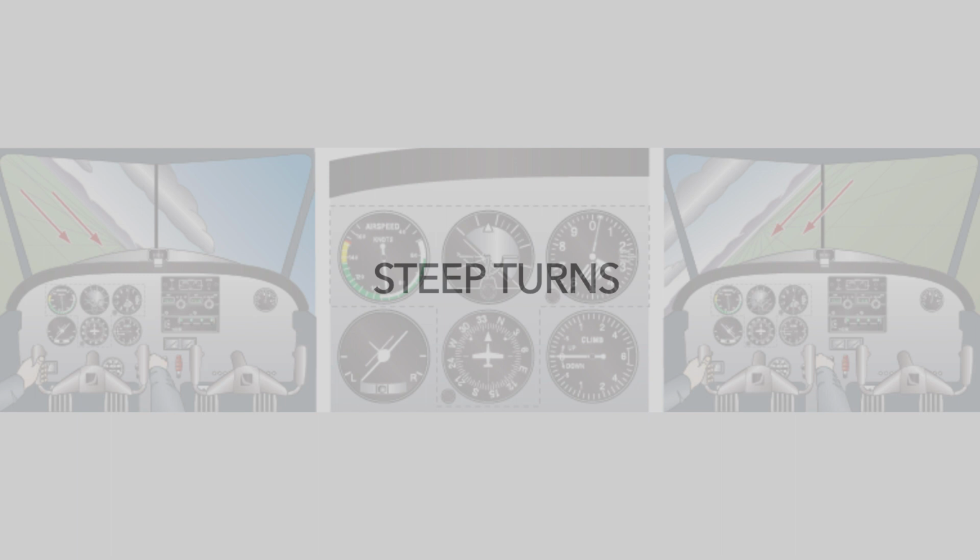3. The byproduct of increased angle of attack is induced drag, which steals energy from the airplane. In order to avoid decelerating and losing altitude, additional power must be applied to rebalance the forces. 4. In a steep turn, there is a tendency for the outside wing to overbank since it is traveling faster compared with the inside wing and therefore producing more lift. As a result, some opposite aileron may be necessary.